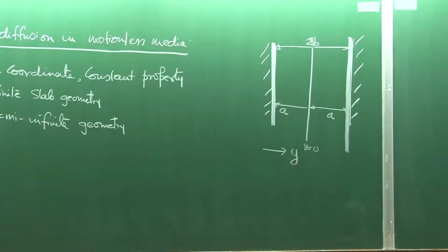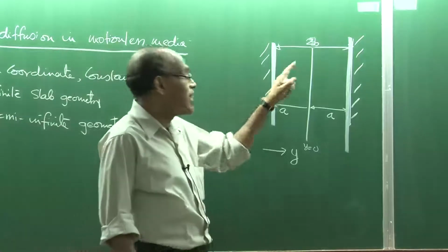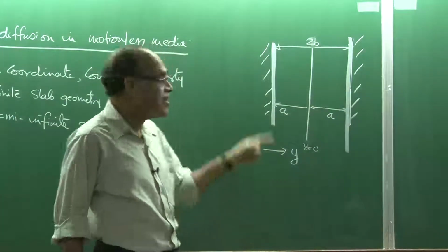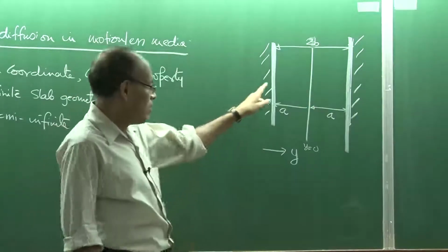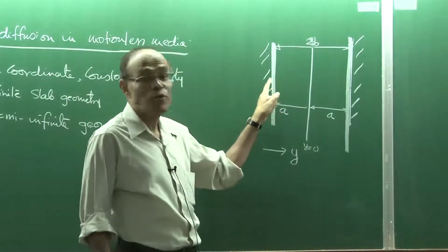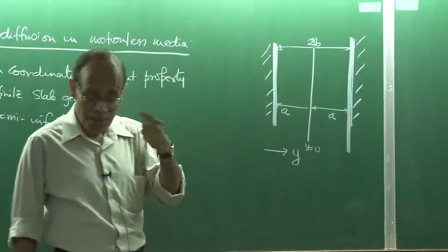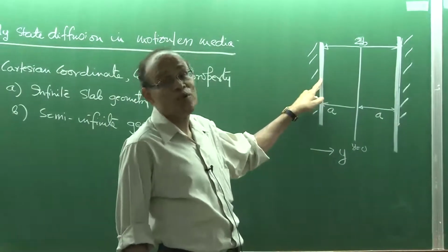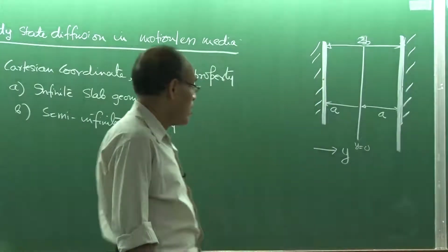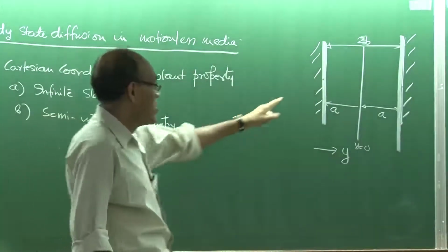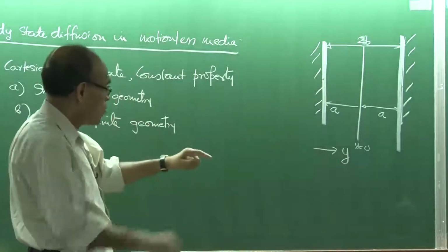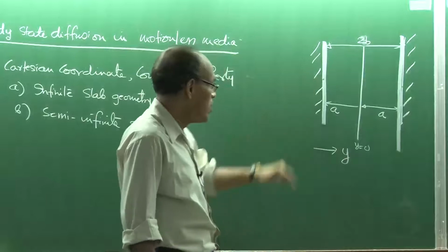As I said, in the context of heat transfer problem, we dealt with this scenario with a fixed temperature boundary condition, and in this case also we are going to deal with the equivalent scenario for a fixed concentration. As I said, and I have been repeating it again and again, how are the concentrations known? The concentrations will be known on the basis of chemical equilibria of the relevant surface reactions that really take place for transfer of species from the bulk phase to the interface.